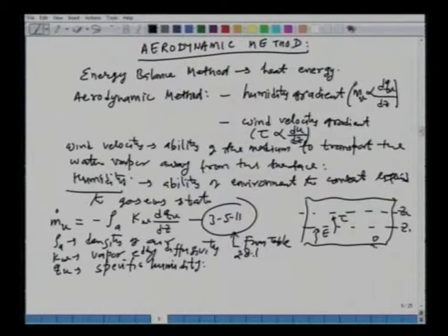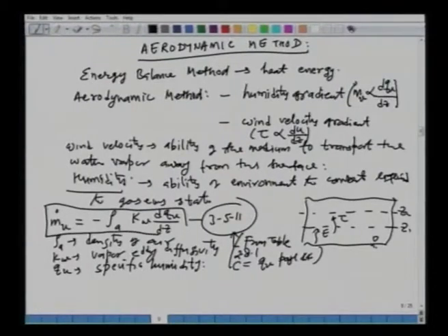So, this is the equation which I have taken from table 2.8.1, and in that equation the concentration C has been replaced by qv, and it is given on page 44. For those of you who would like to verify this, you can go to page 44 of Vennard's book. So, this is the basic equation which will govern the vapor flow rate depending upon the humidity gradient.